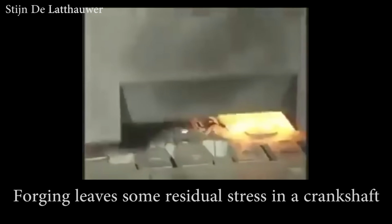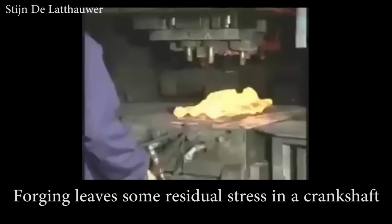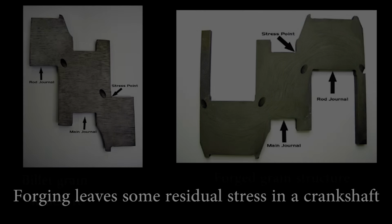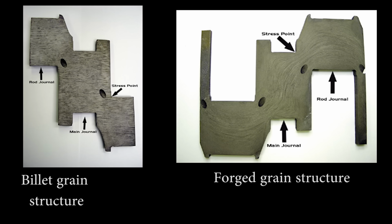Now, during the forging process of a crankshaft, the grain structure of the metal gets deformed, reshaped, and stretched at very high temperatures. This leaves some residual stress in the metal. Now, in contrast to this, billet crankshafts get to retain the grain structure of the metal, and it remains unchanged without any residual stress.